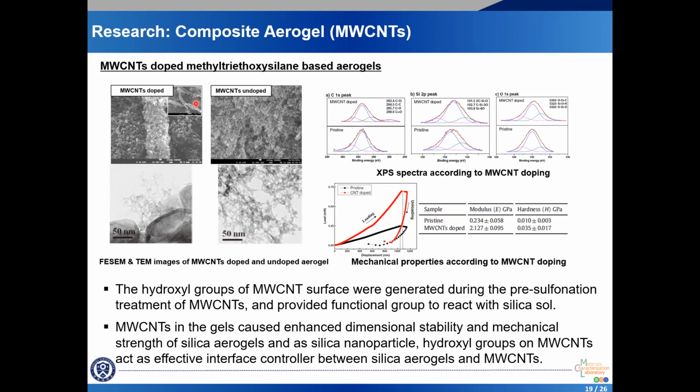From the same image, it was confirmed that the silica aerogel primary particles were kept on the multi-wall CNT from the condensation reaction between the hydroxyl groups of multi-wall CNT and silica aerogels.